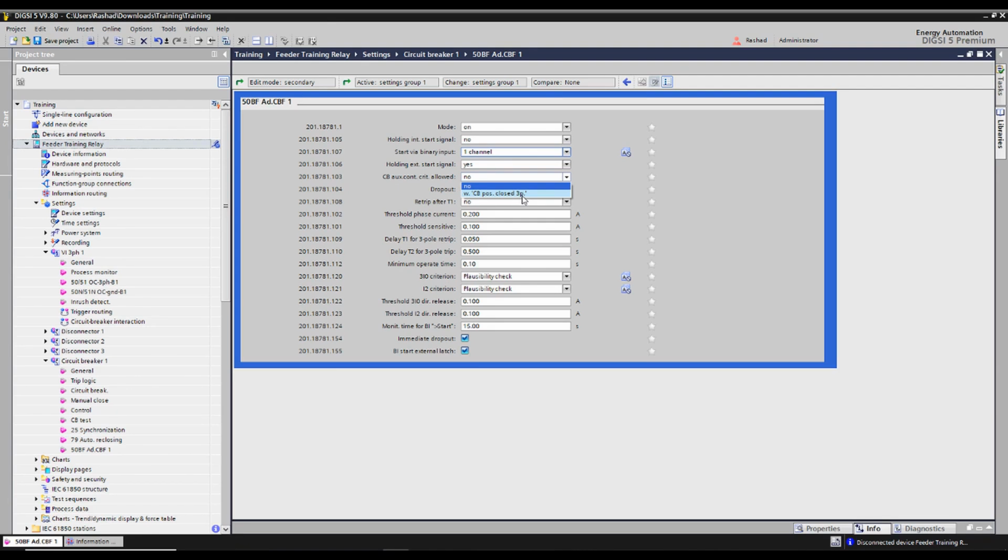All right? Very good. This source could be a protection function related to the flow of electric current, such as differential, distance, overcurrent, earth fault, and other protection functions. And there are other protection functions like undervoltage and overvoltage, among others, which do not necessarily involve the flow of electric current. Also, there are mechanical protections found on transformers and generators. In this case, we call it low current mode or without current mode circuit breaker failure.